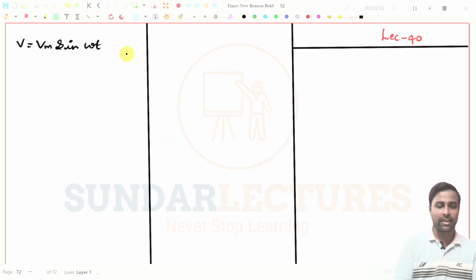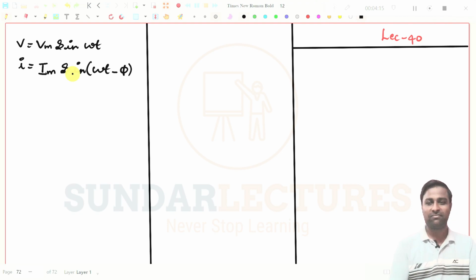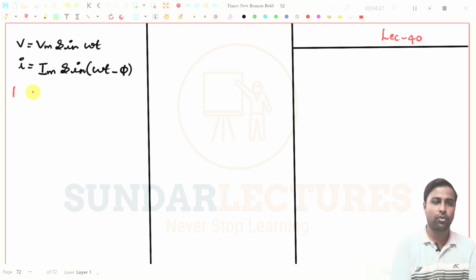So what can I write here? I should be equal to Im sin of omega t minus phi. That's all. Simple to understand, right? So minus phi. So this is the expression for V and I in the RL circuit. Now we try to get the power expression. So, power in the RL circuit.